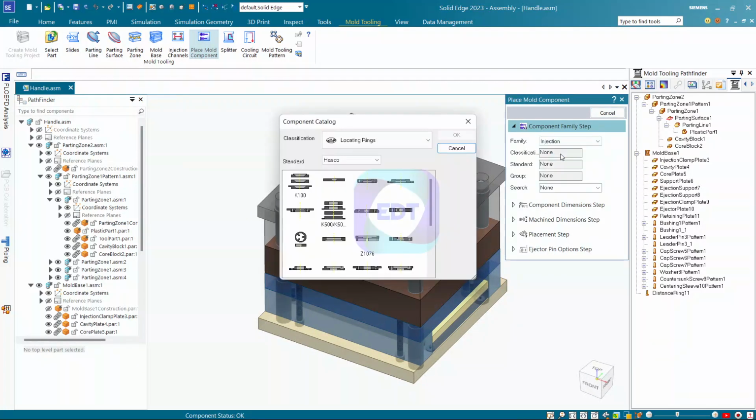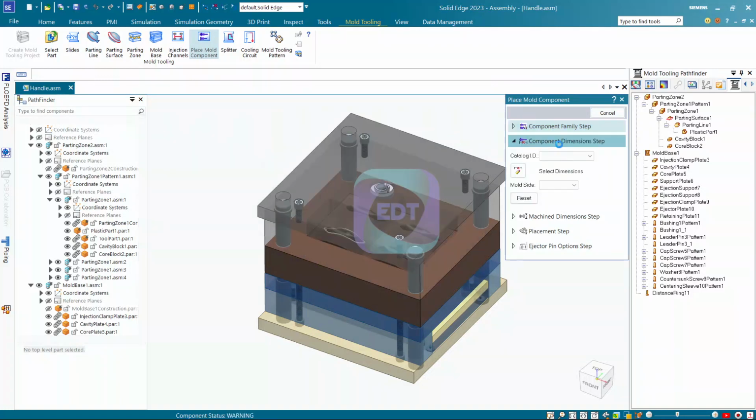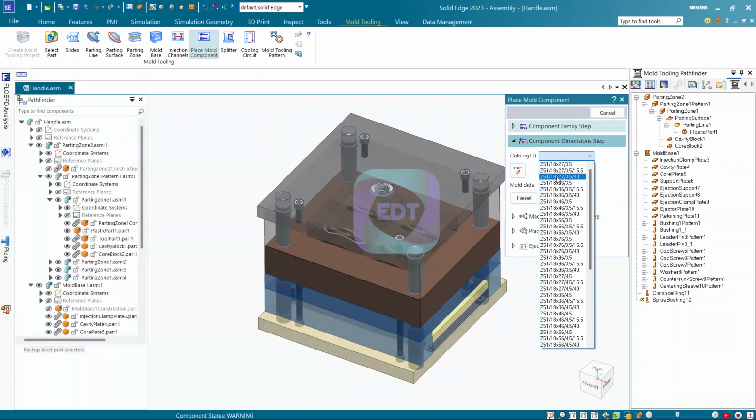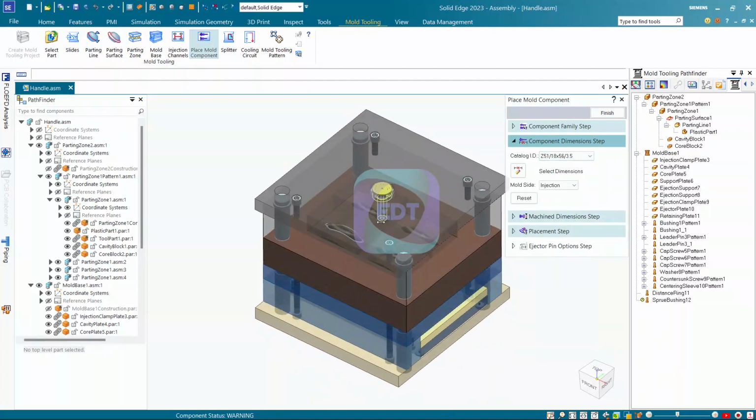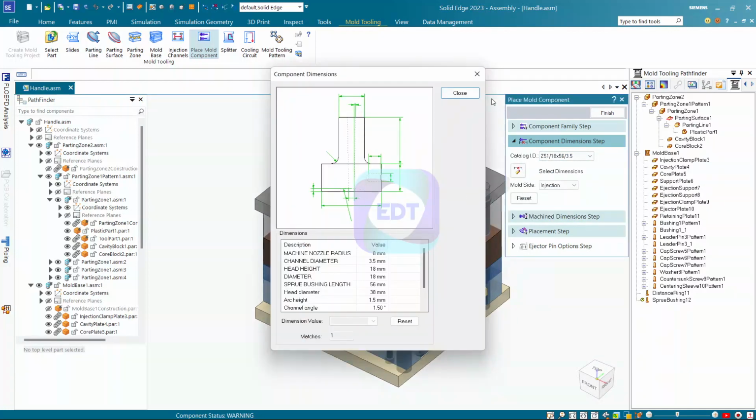Let's say I'll go to injection, and this time I will choose injector. So I will add one injector here with Z51 characteristic. I can choose the exact component from the catalog, and again you can see various components being available here. I will choose a right fit, which would probably be an ideal component for this case. So the length may be slightly smaller. I can go up to any limit I want. I can also change the dimensions at a later point if needed.